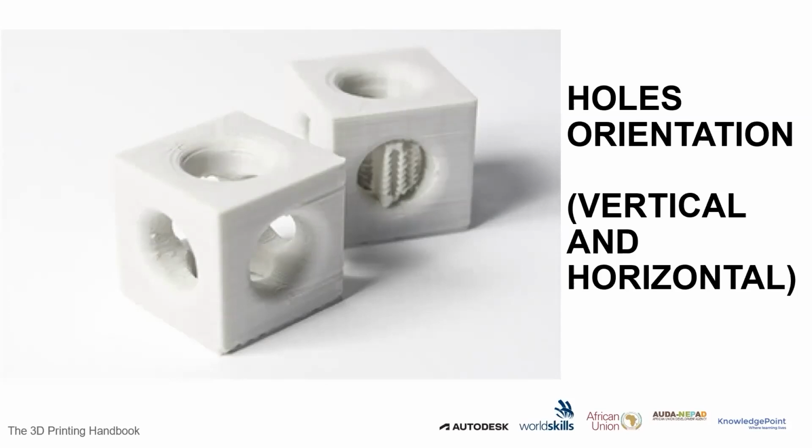But please do not use support for anything less than 5 mm in here, because it's going to be very difficult to remove the support, because a 5 mm hole is very tiny. And it doesn't really require support to print. So please do not use support for such a thing here. But for larger holes, fine, you can use support, because the larger the hole, the more it can deteriorate without support. But with smaller holes, 2 mm, 3 mm, 4 mm, please do not use support.